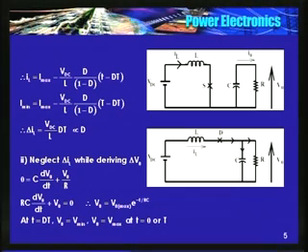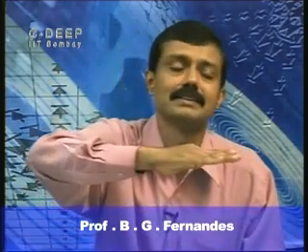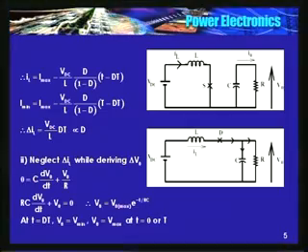It should charge when the switch is open, because we assume that the average output voltage remains constant. It discharges for some time, charges for some other time, so the average voltage remains constant. So IL has to be higher than I naught when I open the switch. So it is minimum when t is equal to dt.